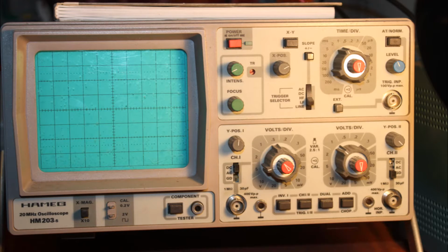There are two main controls on all oscilloscopes. The first of these is called the time base, and this controls how the frequency of a signal is displayed on the screen. The other control is called the sensitivity, and controls the display of the amplitude on the screen. Because the oscilloscope has two inputs, it has two sensitivity controls in general.